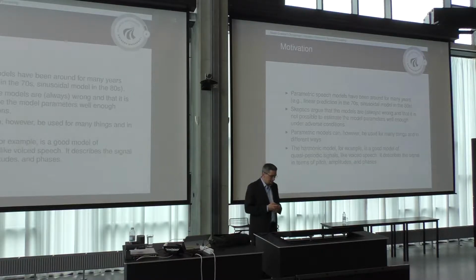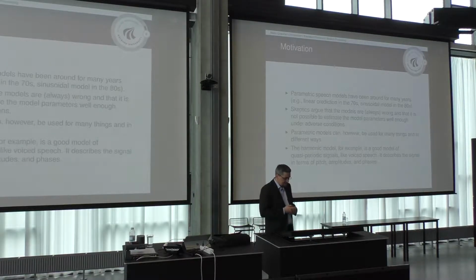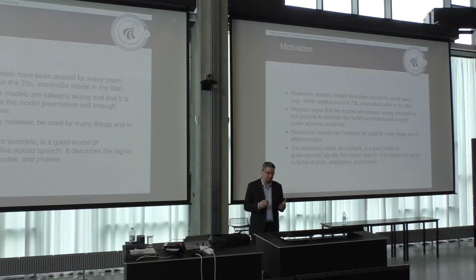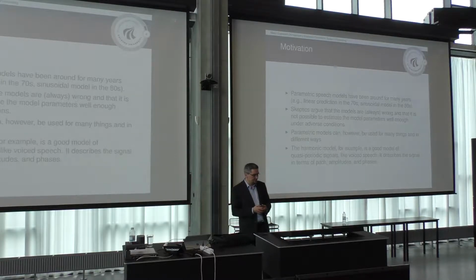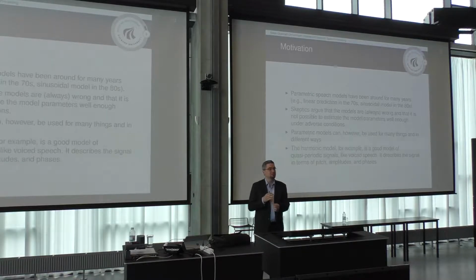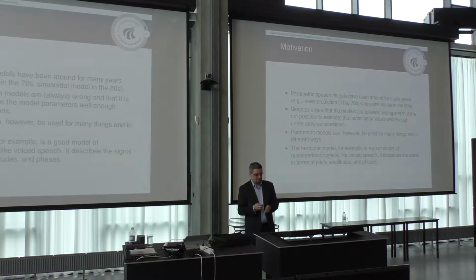And the model I'll be talking about here today is the harmonic model, and that is a good model of quasi-periodic signals. In this case, it would be voiced speech, but it could also be music signals and many other kinds of signals. This model basically describes your signal in terms of pitch or fundamental frequency, a set of amplitudes and phases, and that's it.